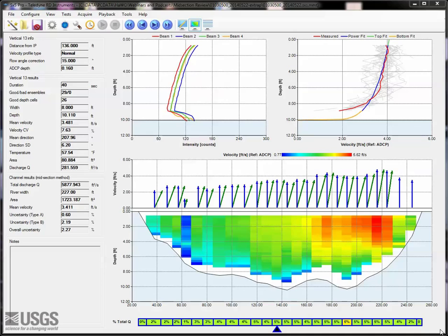In the plots, look for consistent trends of measured data and the extrapolated areas not agreeing. And if there are consistent differences, it's likely a change is needed from the power default. In this data set, we do notice the data on the bottom going towards zero higher in the water column than the standard power fit, causing a large difference between the measured data and the bottom extrapolation.